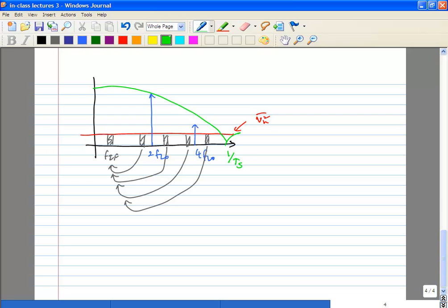So what happens when you increase the width? Obviously there is only a limited amount of noise. It's not an unlimited amount of noise which adds in. So what happens when you increase the size of the transistor? TS drops, which means 1 over TS, the sampling bandwidth, increases. So you actually add in more noise, but the input referred noise floor actually goes down. VN actually goes down. So overall it ends up compensating, so that the output noise due to the switches is independent of the switch width.